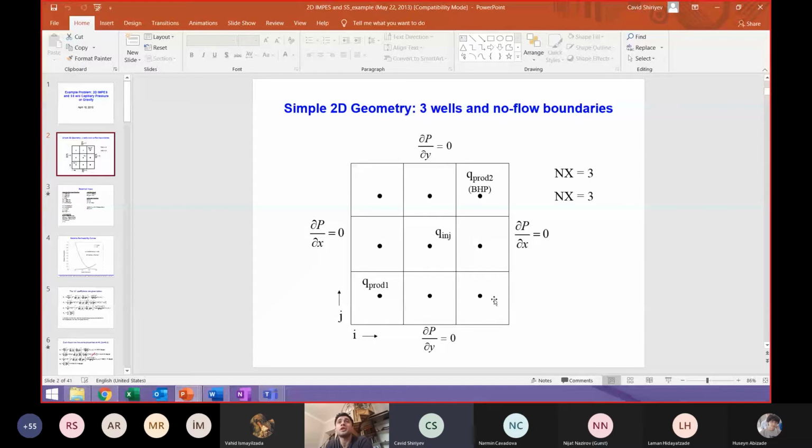Dirichlet boundary condition explicitly states the pressure at the boundaries. But in our case, we are going to have the unknowns at the center of the grid. So even in the Dirichlet boundary condition, we are still going to have the 9 unknowns, but we are going to modify the boundary values, basically the cells at the boundary, according to the boundary condition that we have. Okay, and our grid solver can also solve this scenario with any type of boundary conditions that we have.